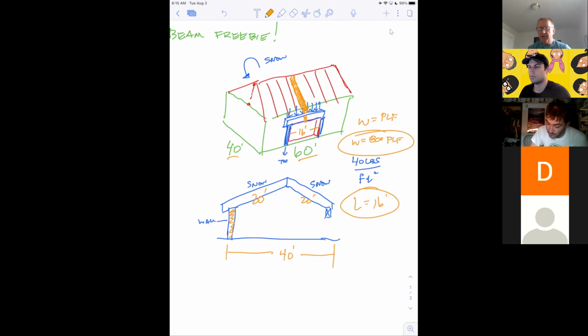I'm not going to go into this again, but if this beam was, say, a 4x12, this is the B and this is the D. And I showed you on your sheet yesterday that the I value that we need is B times D cubed over 12. I'm tempted to show you the calculus about where that beautiful formula comes from too, but maybe after class. I do have something important I need to teach you today. So there's where the I value comes from.